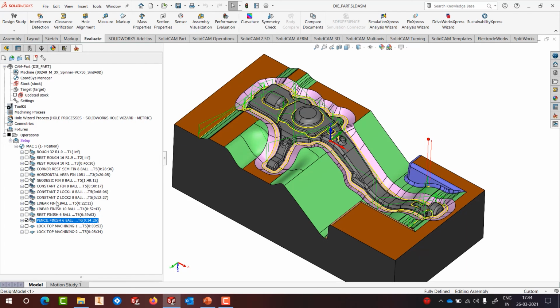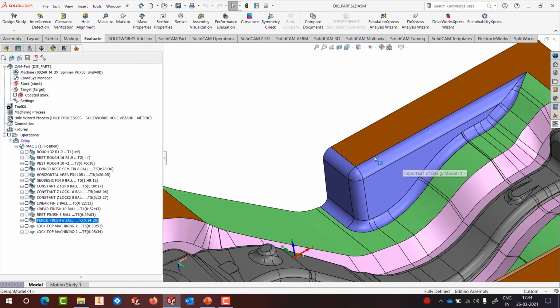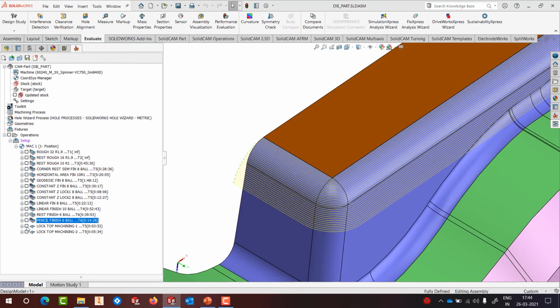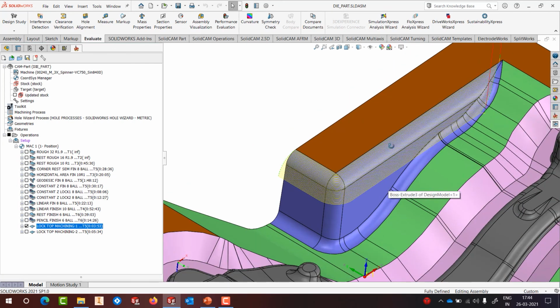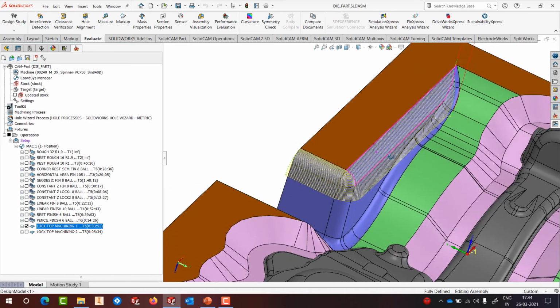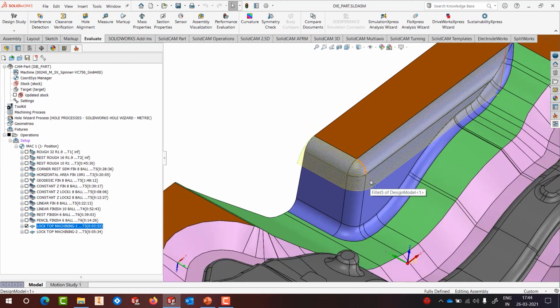And then we have the HSS machining principle, which is basically the surfacing function, which we will see a slide later, where I have done the top fillet finishing. You can see how smooth the tool path is. It starts from one and ends at the other one. So it's machined the entire fillet very smoothly with a ball nose tool. So I've used the HSS principle here.